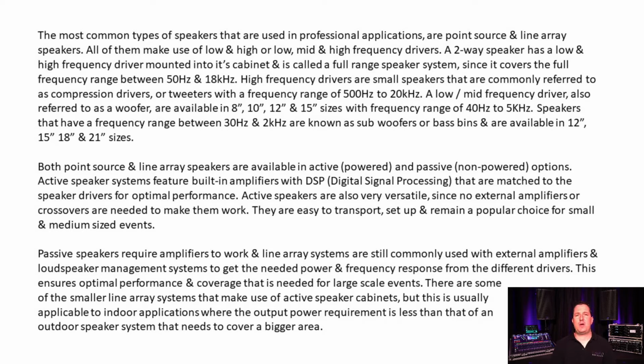High frequency drivers are small speakers that are commonly referred to as compression drivers or tweeters with a frequency range of between 500 and 20 kHz. A low or mid-frequency driver, also referred to as a woofer, is available in 8, 10, 12 and 15-inch sizes with a frequency range of 40 Hz to 5 kHz. Speakers that have frequency ranges between 30 Hz and 2 kHz are known as subwoofers or basebins and are available in 12, 15, 18 and 21-inch sizes.